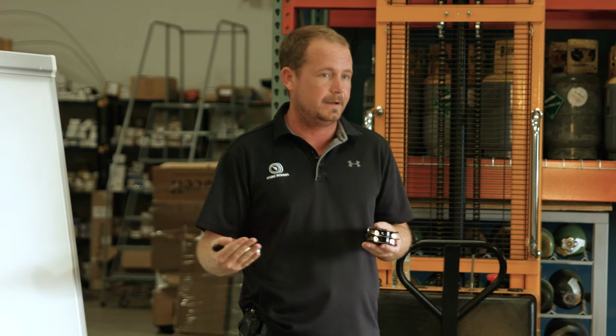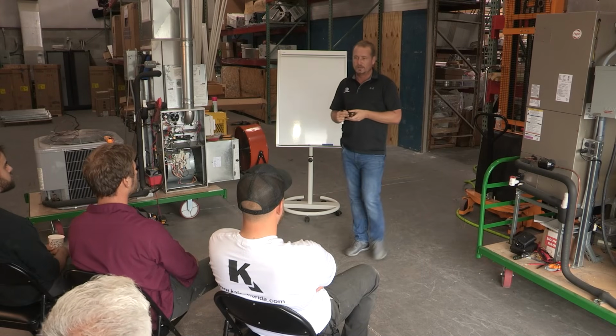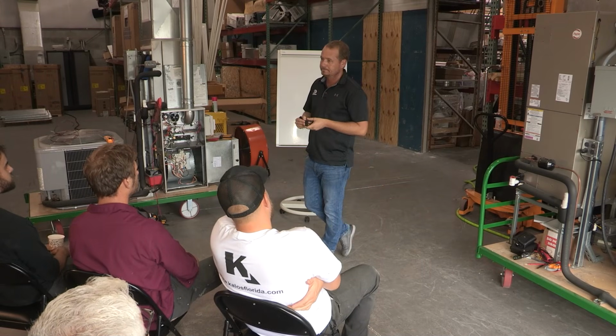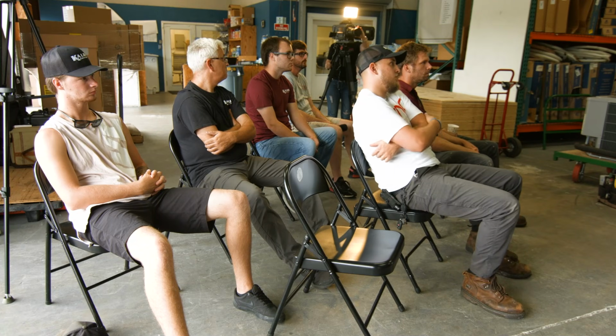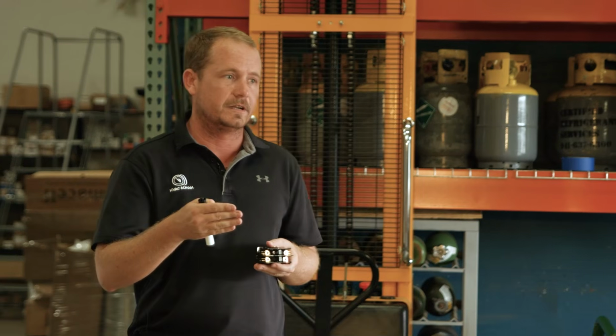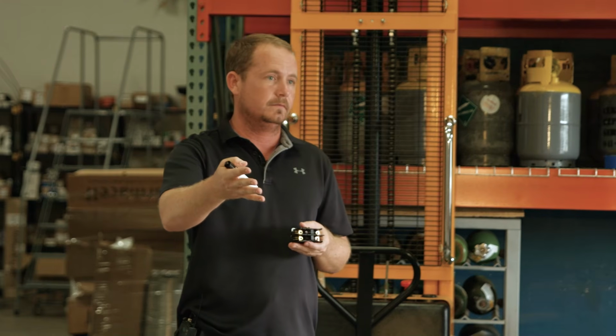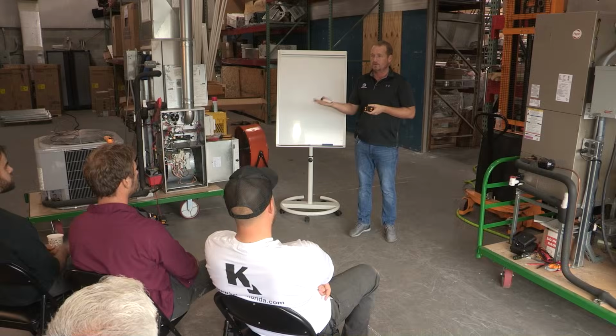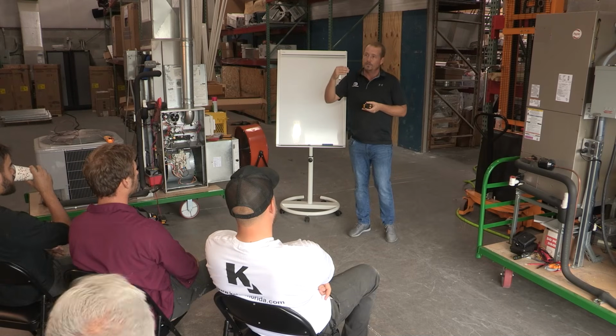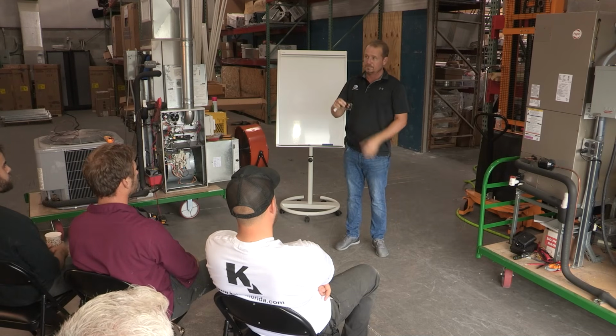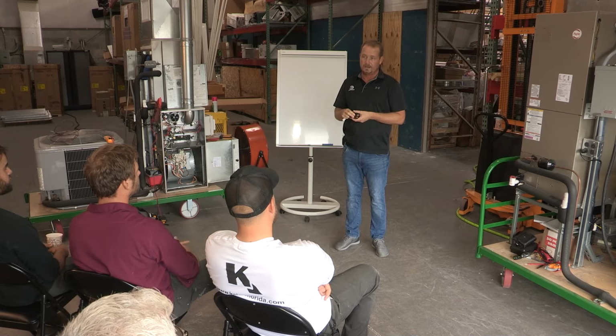But on a heat pump, why isn't this cooling by itself? Because you have a reversing valve. Tanner answered, yeah. You have a reversing valve. And the reversing valve does what? Switches between cooling and heating. Yes, the reversing valve switches between cooling and heating. So the compressor contactor stays pulled in either way, whether you're in cooling or in heating.